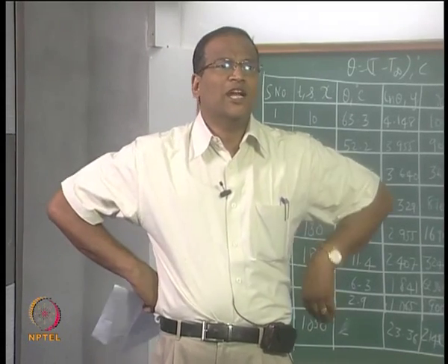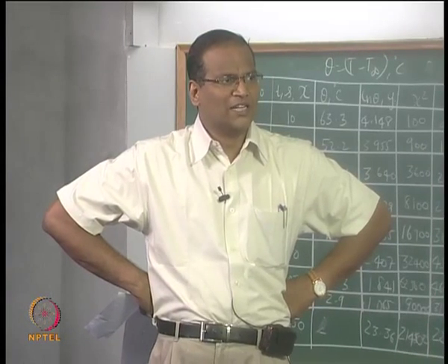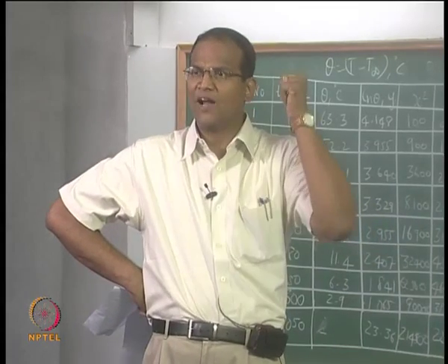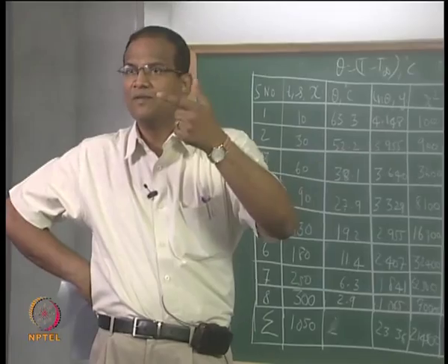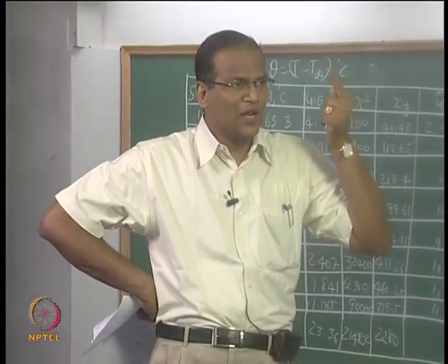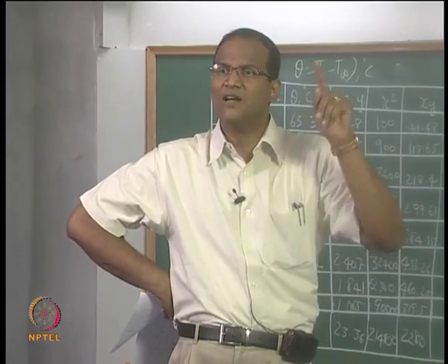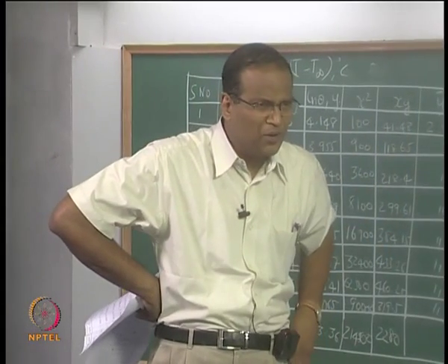See, initially it is cooling down like mad, right? Exactly at the 0th second we do not know what the initial temperature is. That is why it is always subjected to error. So you can use regression and go back and find out this theta I, right? If you have already measured this, then you can verify whether the measurement you have made is accurate or not, because whether it corroborates with your findings from the regression. Are you getting my point?